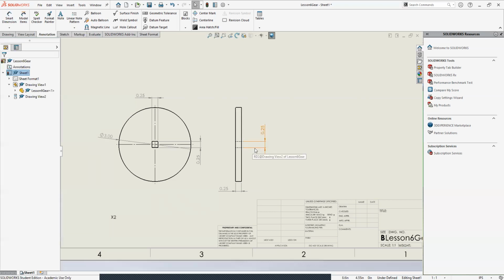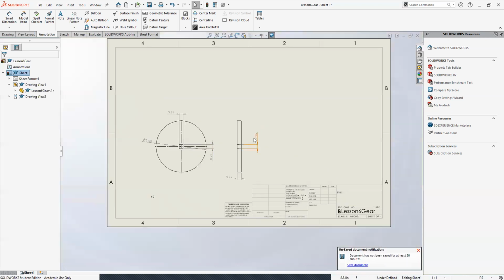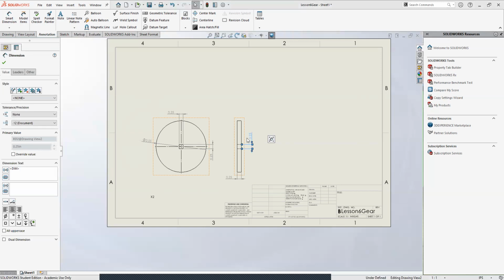Whenever you have hidden lines, that should just be for visual clarification and things like that. Never use hidden lines to do a dimension ever. When we do a more complicated part, I can show you other ways of doing it if you need to, but you should never do dimensions with hidden lines. They're only there for the person getting this drawing to look at and see. Don't use them to add dimensions. So I'm going to delete that.